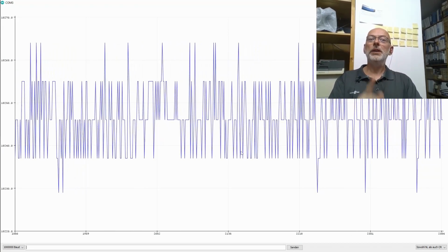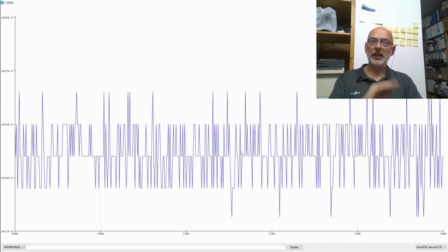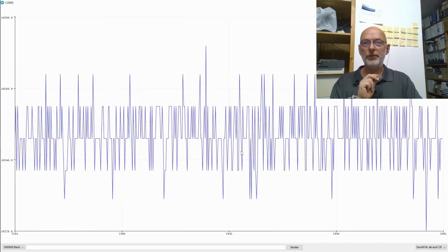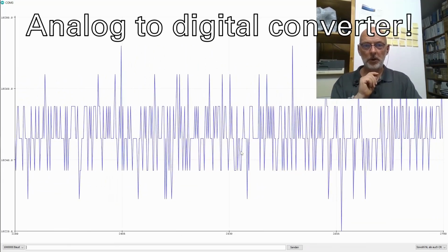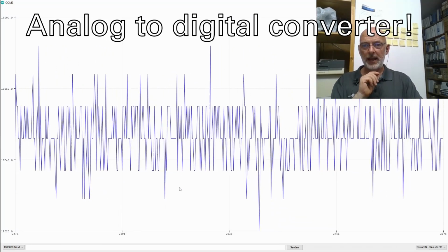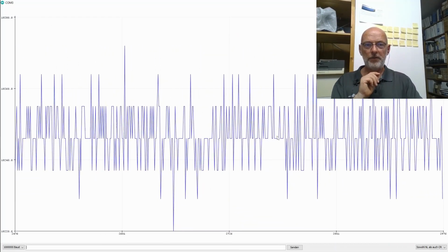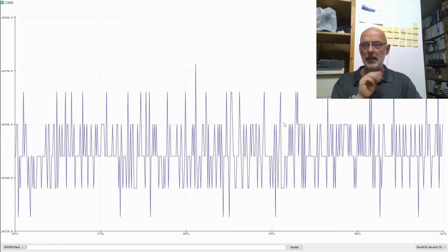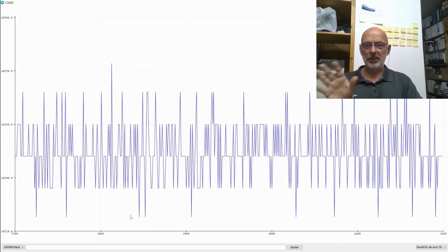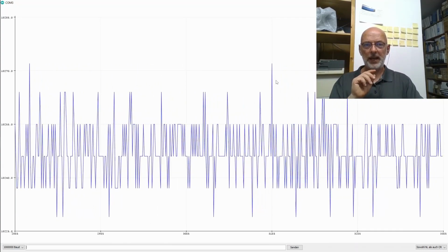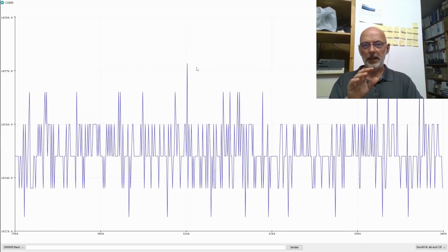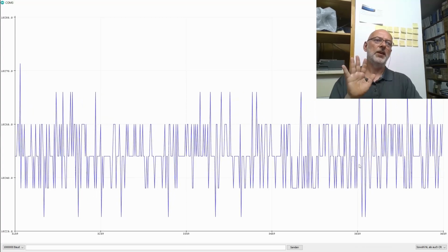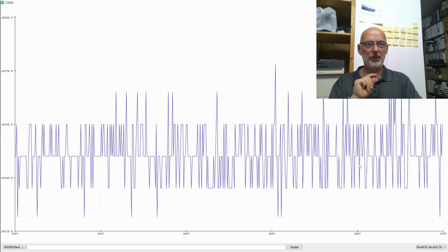Remember, that's only one sample, so basically no averaging. That's directly the digital noise we get from the analog to digital converter. And I say that's about 4 least significant bits. Maybe here's a peak and there's a peak in between. So generally 4 least significant bits, and maybe, if we count these 1 bit here up and down, maybe 6 on the extremes.